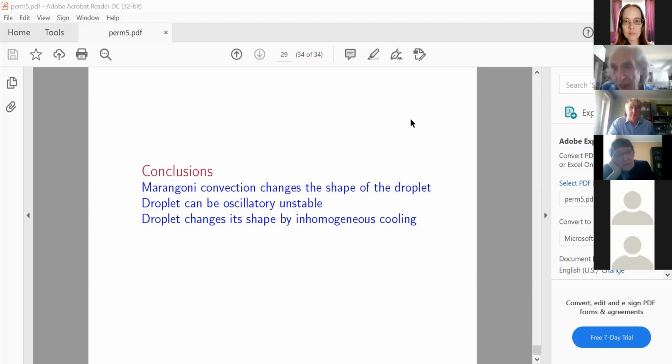But here, in the case when not Rayleigh, not Grashof, but the Galileo number is of order of 1, this limit corresponds to a very, very small Rayleigh number, because the Grashof number is the Galileo number multiplied by this coefficient of the Boussinesq approximation, beta T, which is assumed small.